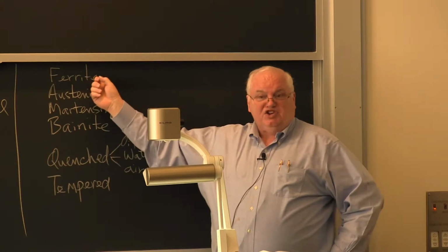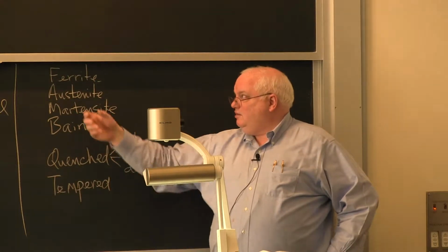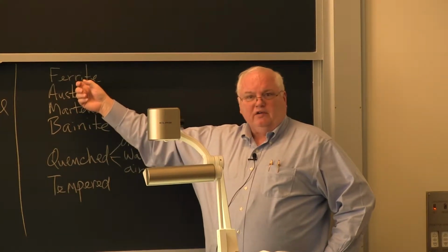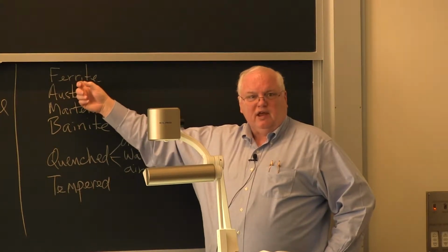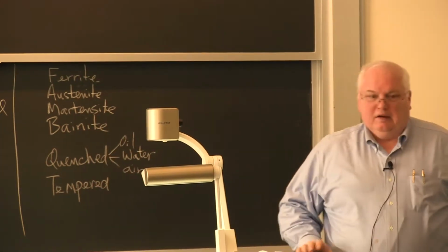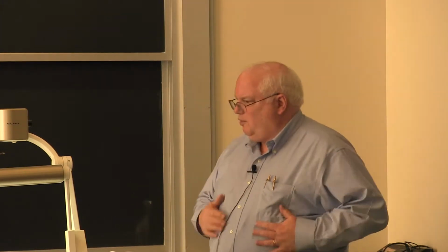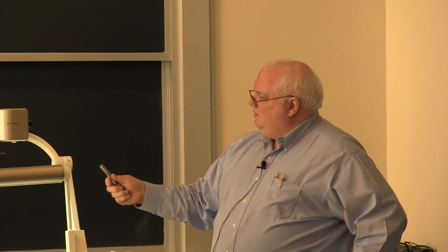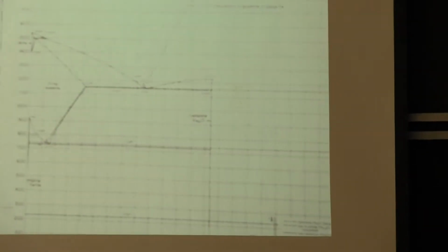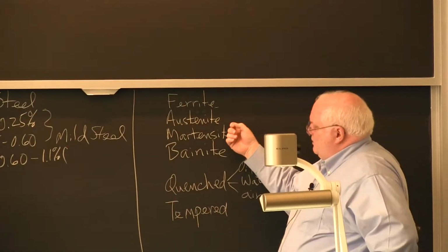Being a geologist, he said, well, it's an iron-based steel. And what do you call things that are iron? You use the Latin name of ferrite, okay, and you put "ite" in to make it a mineral name, okay? So this was ferrite. So low-carbon steel, the alpha form, which is from the phase diagram over here, is called ferrite. And it's unremarkable other than the grain size.